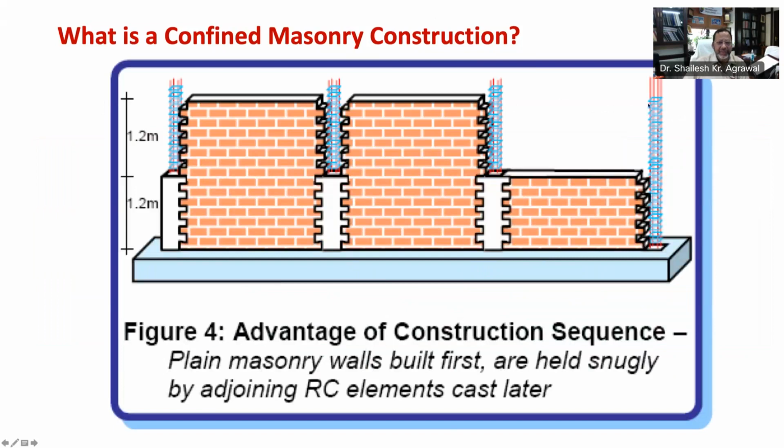RCC confining elements enhance stability and strength of brittle masonry walls, that is, interaction between masonry walls, structural integrity and containment of earthquake damage within masonry walls. These advantages lead to ductile earthquake performance of confined masonry houses over those of alternative concrete and masonry building technologies with relatively lower level of technical efforts.